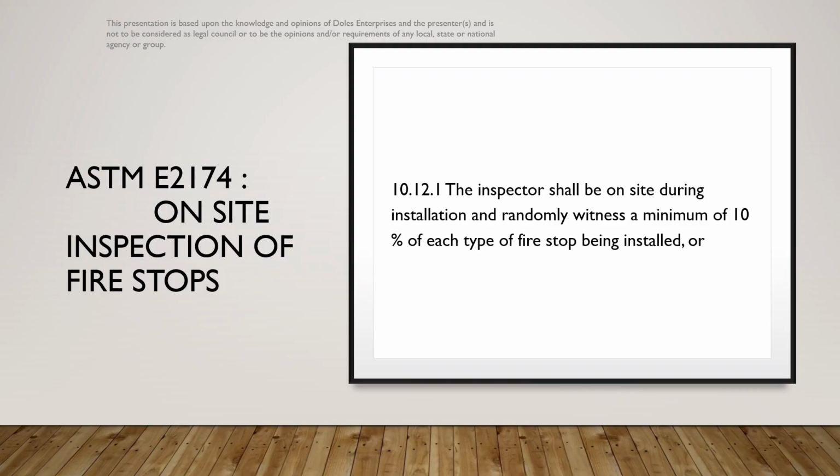ASTM E2174 offers two methods of conducting inspections. The first one is that the inspector shall be on site during installation and randomly witness a minimum of 10% of each type of firestop being installed.